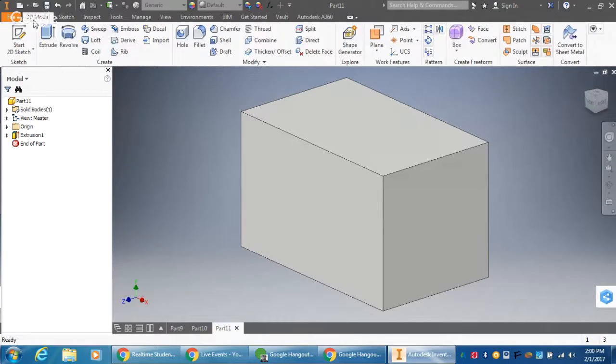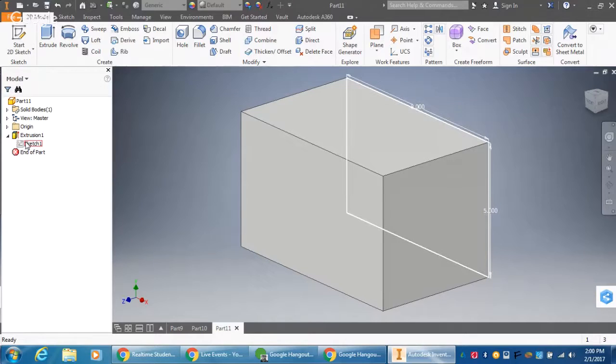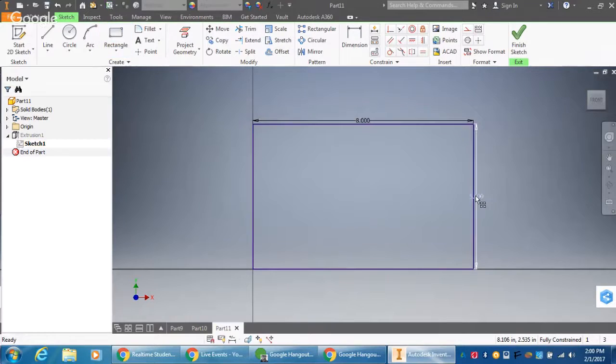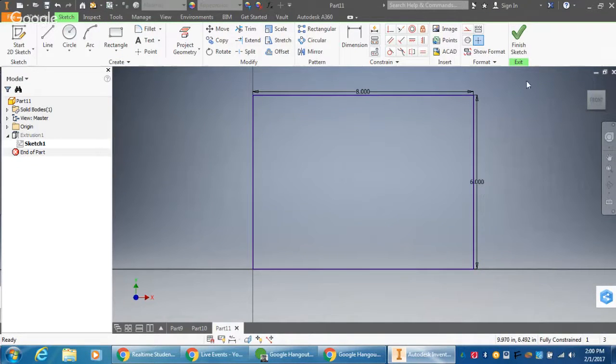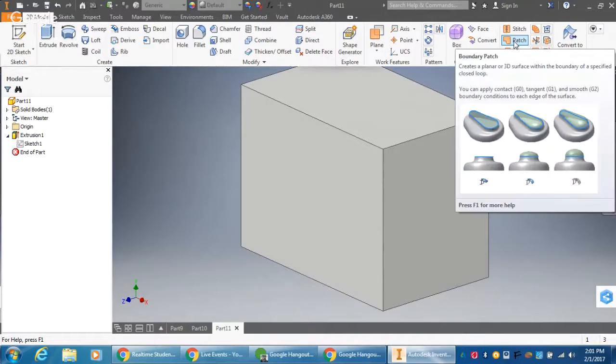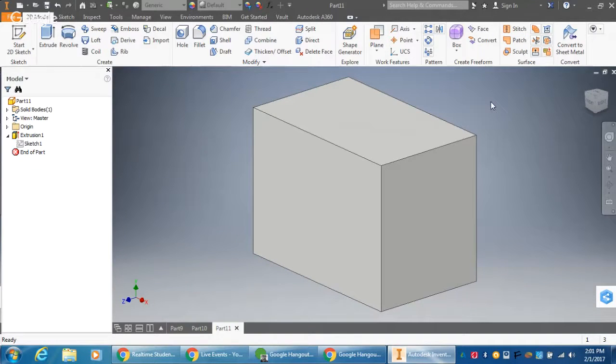That's why it's important. I'm going to go over here and click the flyout on this extrusion 1, and you can see that sketch 1 has been consumed by that extrusion, but it still exists. So if I did something wrong, I can just double click and change it, because this measurement is really supposed to be 6, not 5. And watch what happens when I just hit enter, finish the sketch. Whoa, it automatically adjusts. Cool, huh? It's like you're learning new stuff about this software every time I build something new.